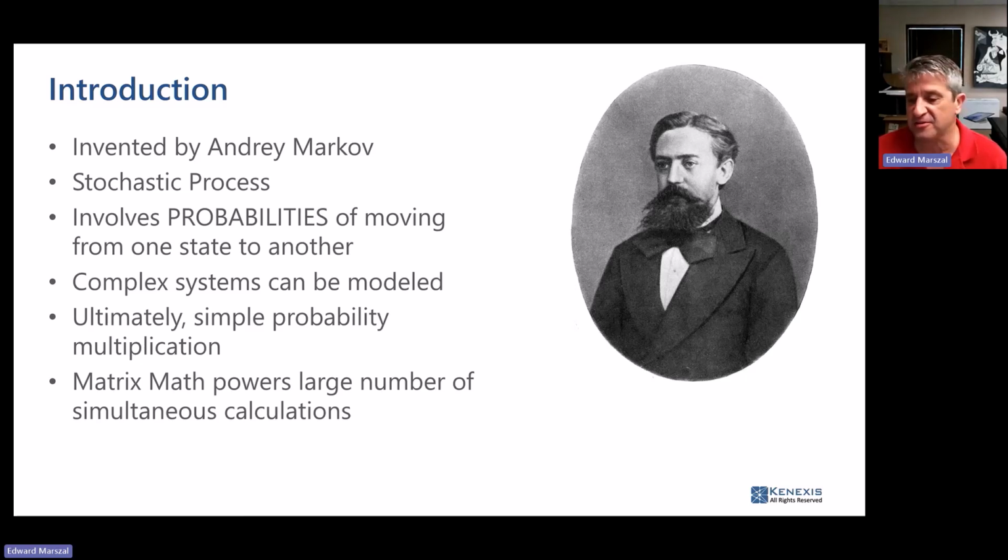We have analytical solution equations. The value of Markov modeling comes from really complex models, really complex situations where we have a lot of redundancy, a lot of diagnostics, a lot of weird repair schemes that we don't have equations for, and we don't want to take the time to create the equation. So instead of doing a symbolic solution where we create an equation, we're going to basically do a numerical solution, quick and dirty. That's what's happening when you're doing the Markov modeling.